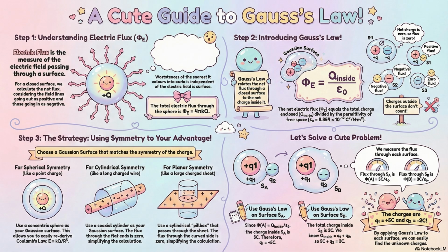Everything. And they have that other weird quirk, preconditioning. If they sit on a shelf for a year or more, you're supposed to gently power them up. Why is that? The dielectric is an incredibly thin oxide layer. If the cap sits unused, that layer can degrade. If you just slam it with its full rated voltage, it could short out. Gradually applying voltage allows that oxide layer to self-repair.